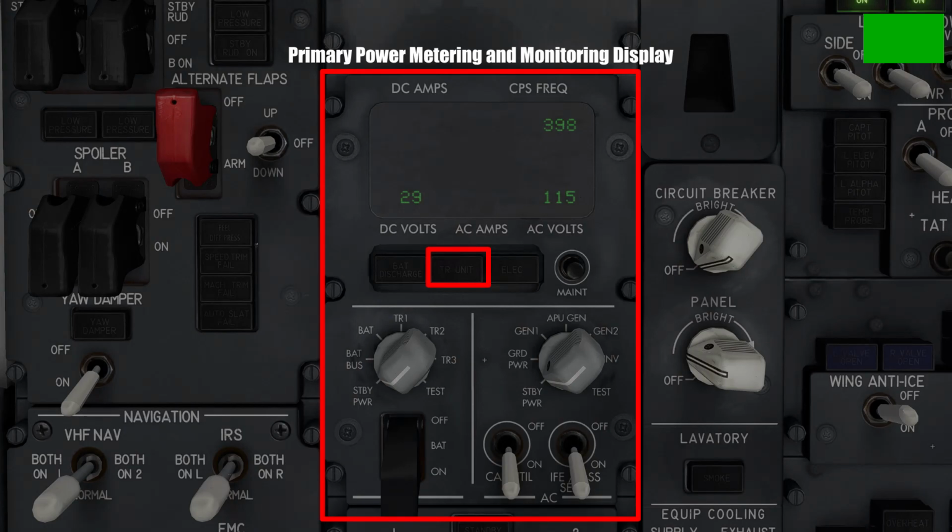The second light illuminates when there is a problem with the onboard TR unit, or the transformer rectifier unit, which is responsible for converting AC power to DC power. This third light illuminates when there is a fault with the electrical system as a whole. This button is a maintenance button, which is only used by ground crew and certified engineers when a particular part of the electrical system needs to be fixed.